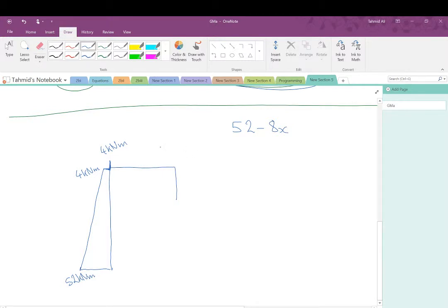So the next equation for this part of the frame is going to be x squared minus 8x plus 4. Now, to make sure it is right, I can put 0 into this equation, and I get a value of 4, and that also matches this 4 kilonewton meters. So I know I'm on the right path and getting the right answer with this question.